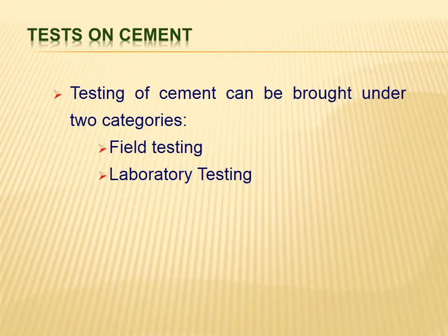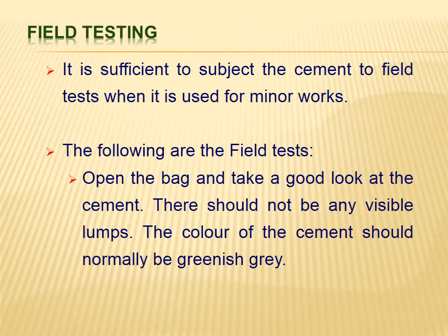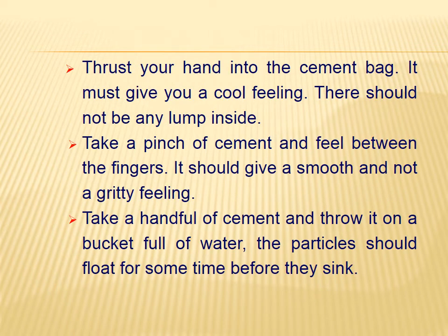Then about the tests on cement. The test can be a field test as well as a laboratory test. In the field, open the bag, touch and see. There should not be any lumps. Color should be greenish gray. These are the other procedures.